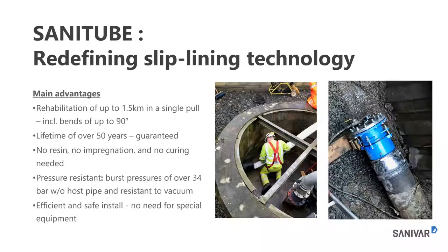But certainly there is the ability to regularly pull through bends of 45 degrees plus. It would depend on the radius, whether they're sweep bends or tight elbows, and indeed on the diameter of the lining and the hose pipe before we could commit fully.